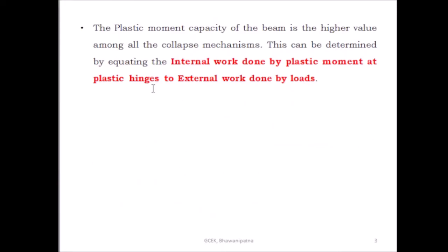The plastic moment capacity of the beam is the higher value among all the collapse mechanisms. This can be determined by equating the internal work done by plastic moment at plastic hinge to the external work done by loads.